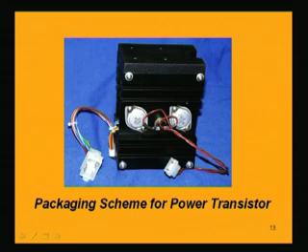So basically what is there? One transistor, which is the device, will first be put into a case, and that case will again be bolted into the heat sink. So the flow of heat is first from the junction of the device to the case, now the case to the sink, and then finally the sink to the air.